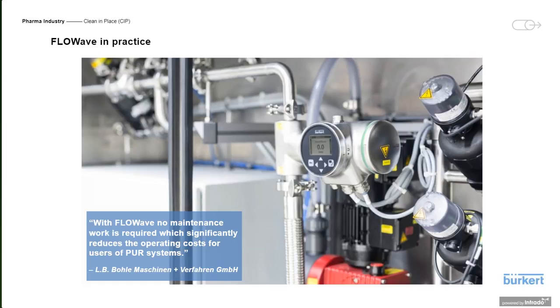Again, another customer testimonial in terms of maintenance. One, the fact that it is full bore technology. There's nothing in the flow path that can fail, including soft parts and gaskets. So in that case, it's relatively maintenance free. If you look at the diagnostics capability that the Smart Top has built in, you can use that a lot for predictive maintenance. And of course, the calibration aspect, it's quite easy to calibrate.